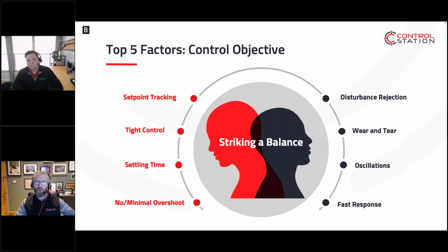You leave it at a point where it's reactive, responsive, but it's not stable. If the process moves at all, it'll drift out of it. It's something I've noticed has drifted in as our PLC processors have gotten faster and more capable. Everything has sped up, and the expectation that the PID should speed up as well in its response has drifted into those tunings.